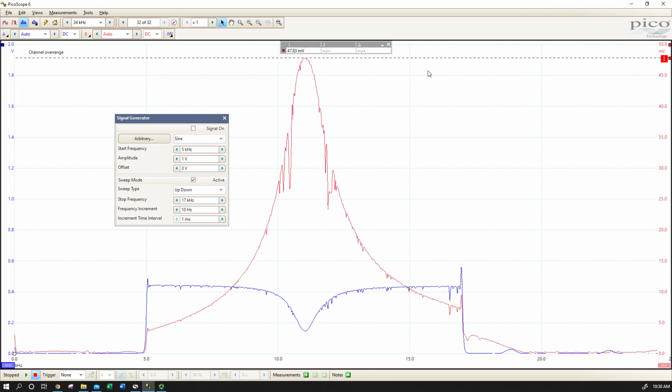We're seeing a voltage drop of about 50 millivolts at resonance versus our whole circuit of 104. So again, a little over 30% of our total circuit voltage drop is the resistor as opposed to the two reactive elements at our resonance point.